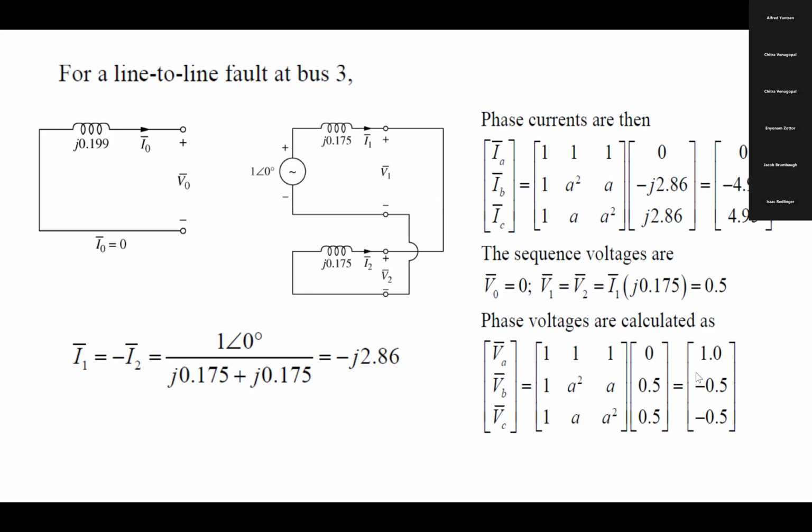So after you connect the circuits, trace the circuit. Current coming out from the source goes through the positive sequence impedance, follow the line, it comes through this impedance, follow the line, it gets back to the source. So current is not getting divided anywhere.